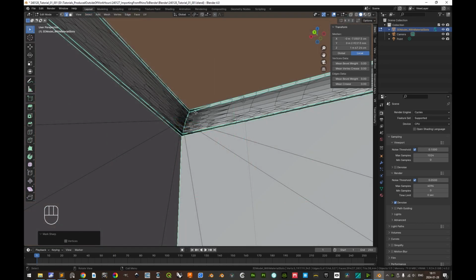All sharp edges will have their vertices' normal directions split between any bordering surfaces, which means that even if there is only one edge between two bordering surfaces, the render engine will interpret the vertices of that single edge as two separate sets of vertices with independent normal directions.